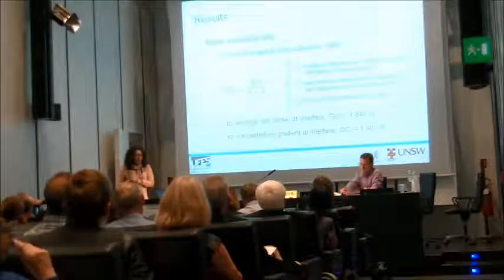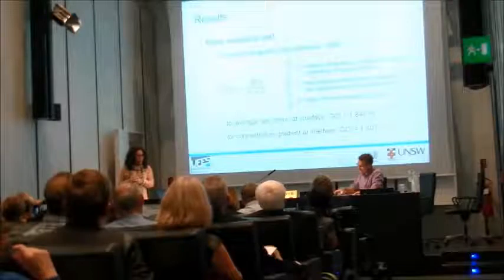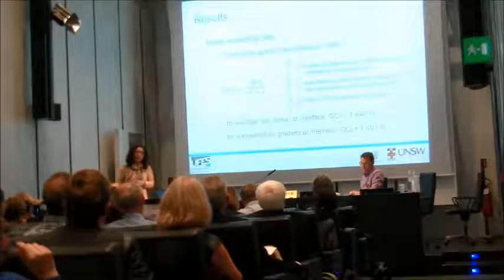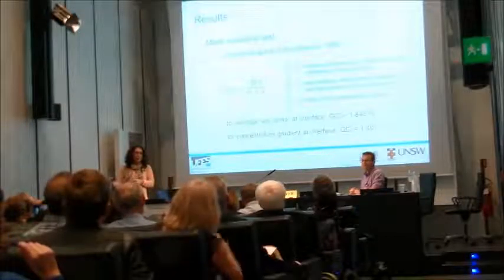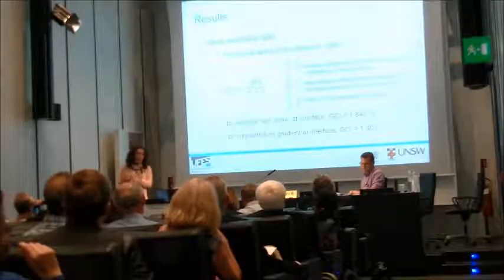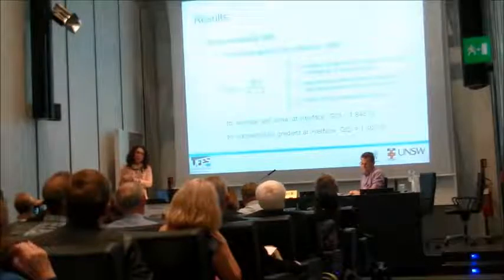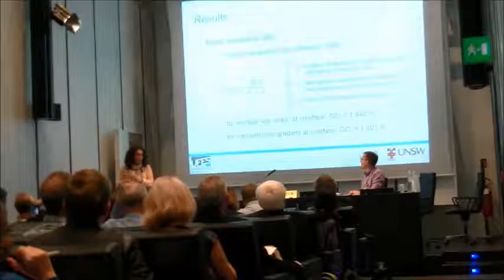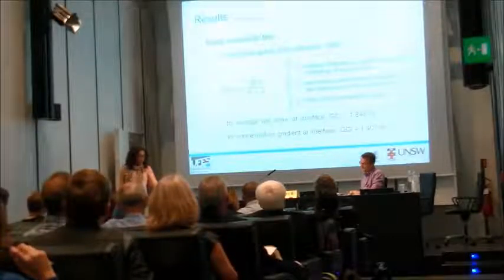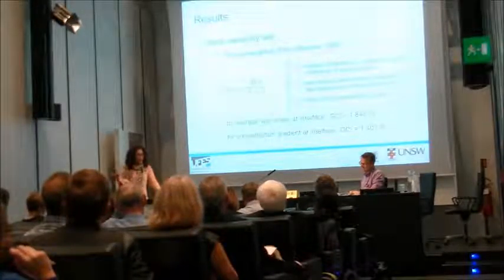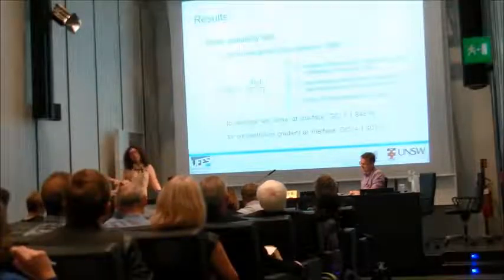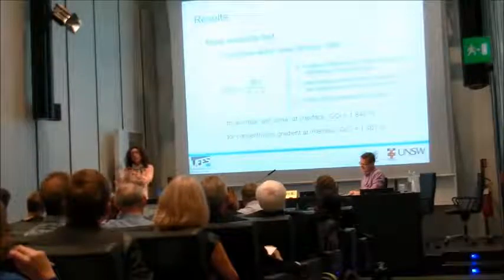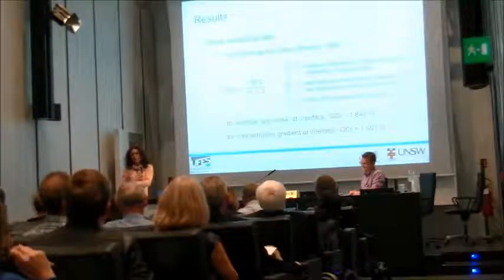For all the simulations, we analyzed the convergence, because then we know that we reached the final result. After running the numerical simulation, the solution is not going to change. That's what the convergence test is there for. So we were certain about the mesh and certain about the convergence. It means that we did the simulation correctly. It doesn't mean that we modeled it correctly. It means that the numerical simulation is correct.